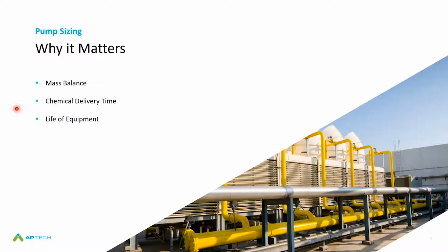If you're demanding that pump to be pumping full bore for hours on end every single day, and it only gets maybe a couple of minutes break here and there, the lifespan of that pump is going to be diminished very rapidly. A pump that might last for 5 years might only last for 6 months.